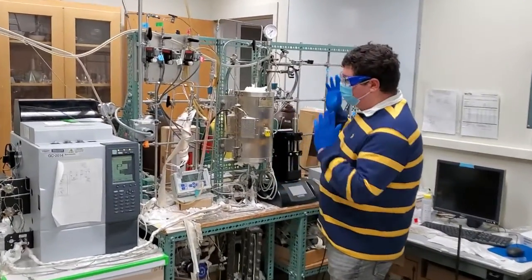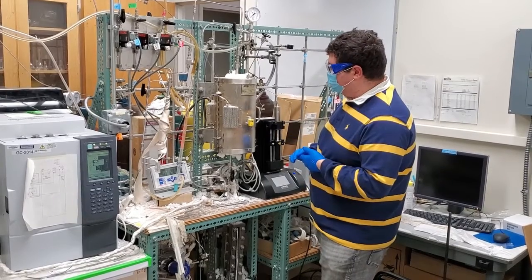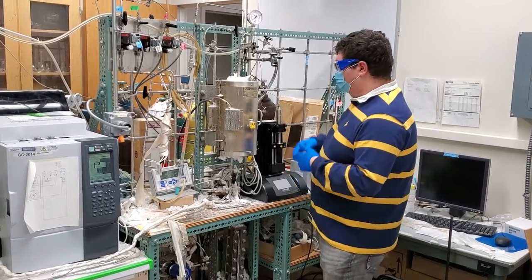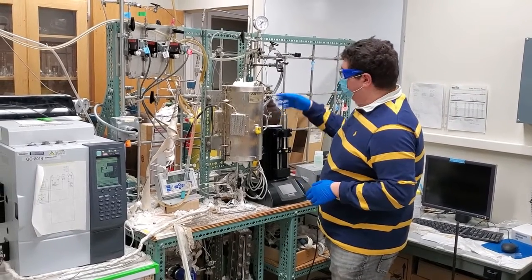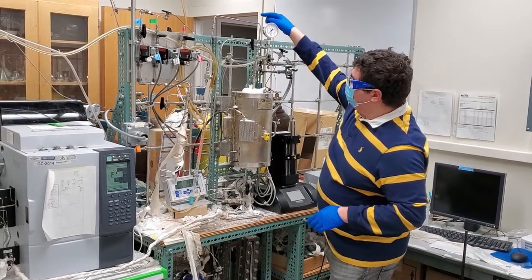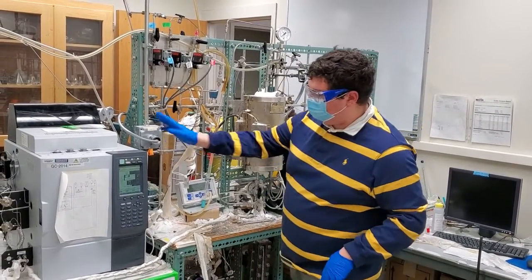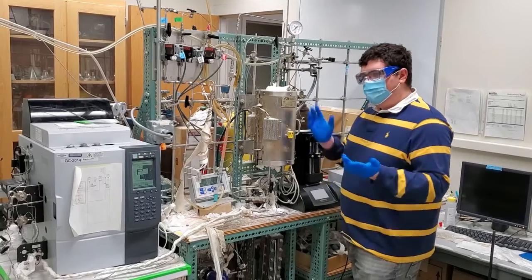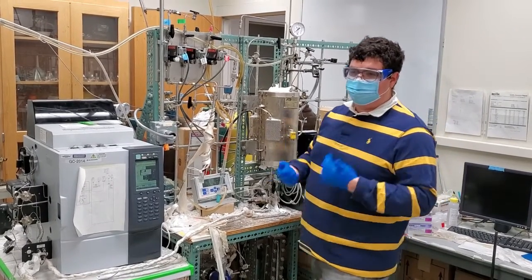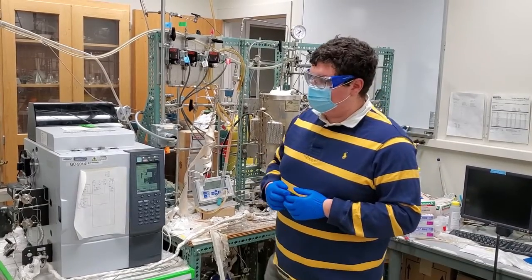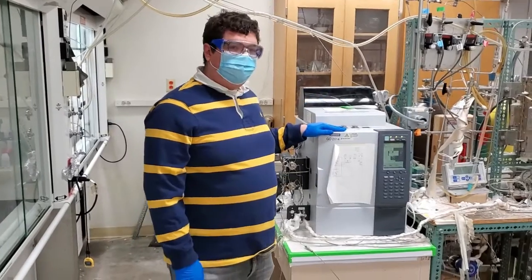This is a methanol synthesis reactor. We study this in a stepwise conversion, where here we flow in the liquid methanol that then gets evaporated by mixing in with helium, and then we can, through this online GC-FID, measure how much methanol we are producing, and compare that to some of the predictions based on the phase diagrams and active sites that we model.